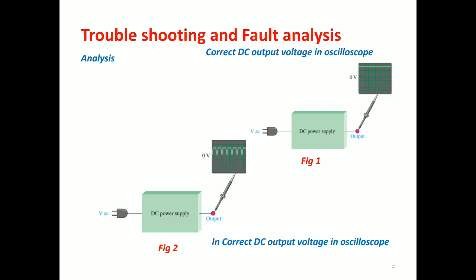Next, make sure the fuse is not blown. The second thing is to be cautious that the fuse is not blown. And in the case of a battery powered system, make sure the battery is in good working condition. You have to assure that these 3 things are suitable for working, then you can go for the next process.